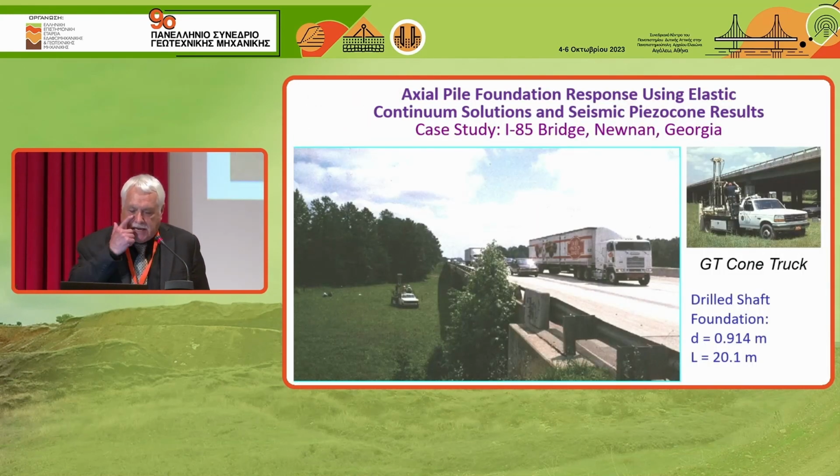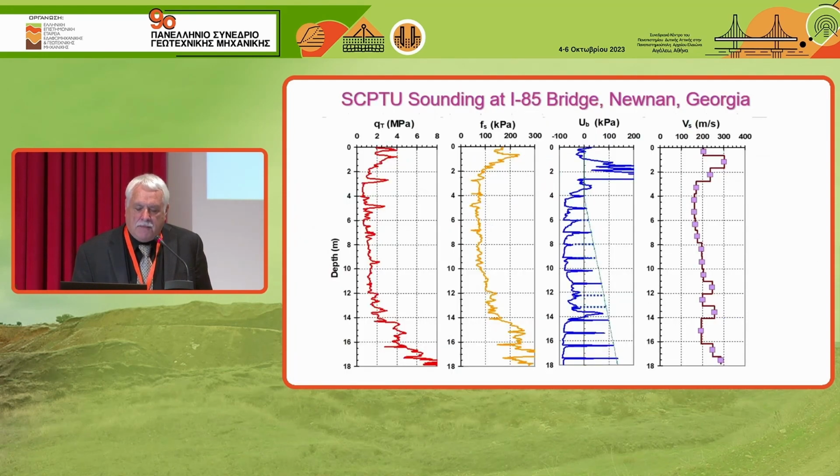And so here's an example from Georgia. This is a site about 45 minutes south of Atlanta. It's an interstate, I-85. You see there's a cone truck, and I have a drilled shaft foundation with the dimensions shown in the lower right. Here's the seismic piezo cone that we did at that site.